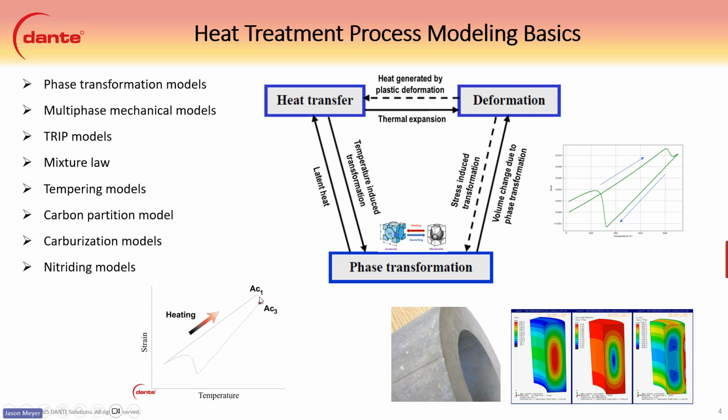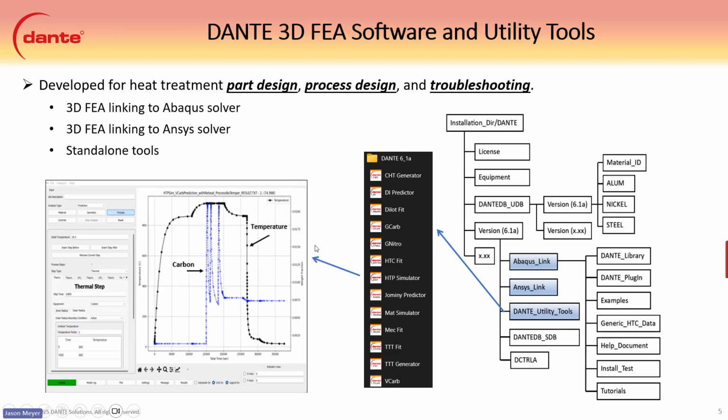And down here at the bottom, there's a little bit of an animation that shows a dilatometry sample animation that shows when you heat a sample, it grows. It gets larger, obviously. And then with steel, it transforms to austenite at a certain point. And once that is complete, you can cool the material down to form diffusive phases or martensite. This example shows a martensite transformation here, and we have a volume growth from that martensite transformation. So when we have the heat transfer, it obviously increases in size, but also when you have phase transformations, you have a volume change due to that phase transformation. And that's really what makes it really complicated as far as controlling distortion in heat treatment. Today, we're going to be talking more about the heat transfer and the chemical transfer phenomena, using HTP Sim to model processes.